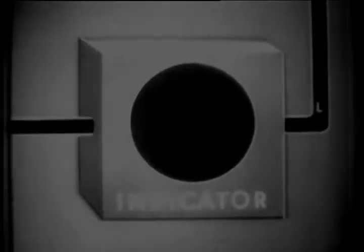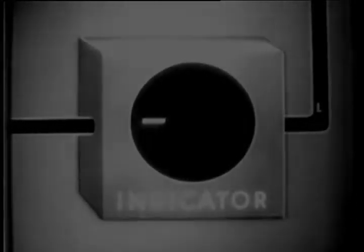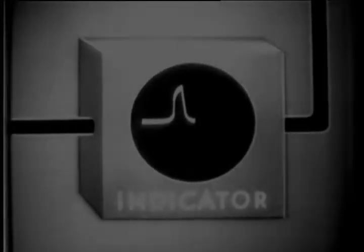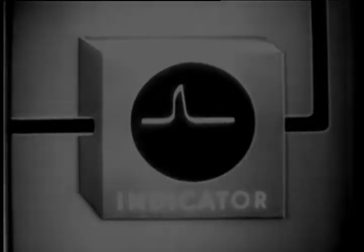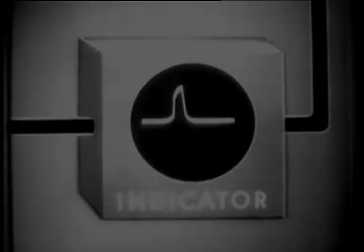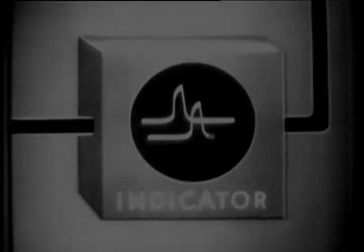Before they appear on the scope, the indicator must also be prepared to receive two echo signals and display them separately. Here's how the indicator works. When a pulse was sent out through the left lobe, at the same time part of that energy was sent over to the scope where it began forming the baseline. Thus, when the echo from the left lobe returns, it forms the pip on that baseline. When the lobe was switched and the pulse went out through the right side, part of that energy was sent over to the indicator also and began forming another baseline, so that when the echo from that pulse returned, it formed a pip on its own baseline.